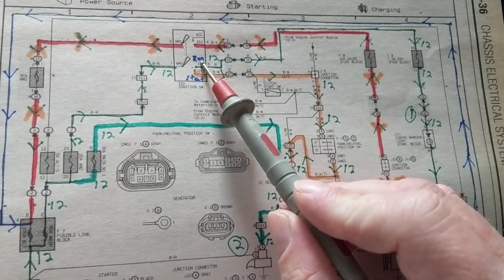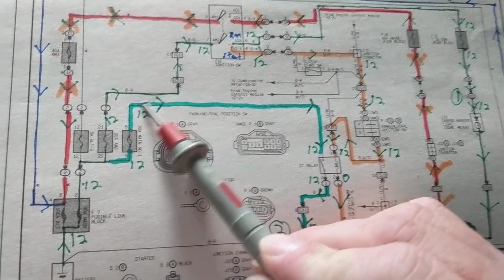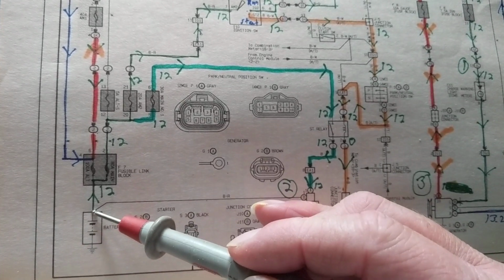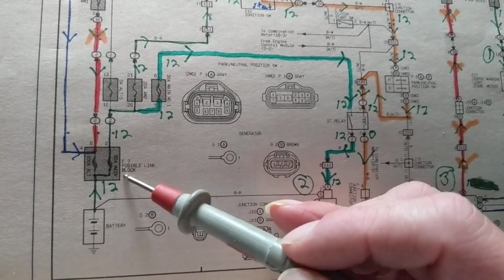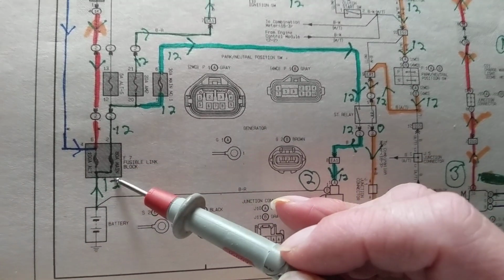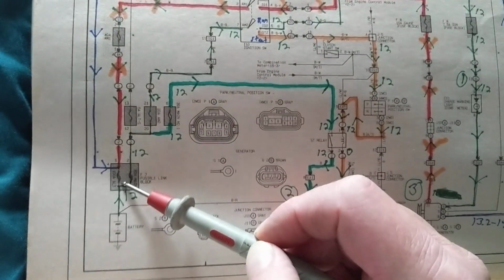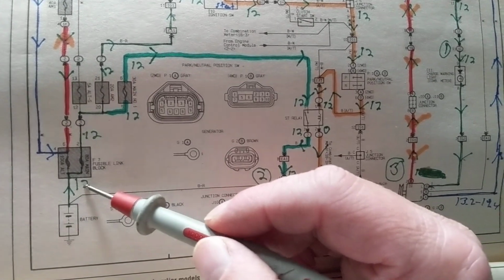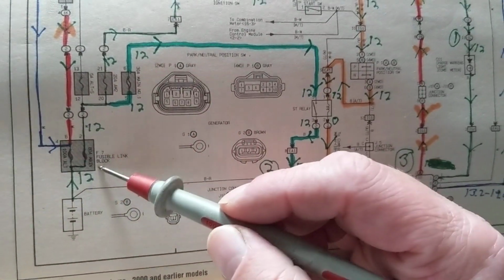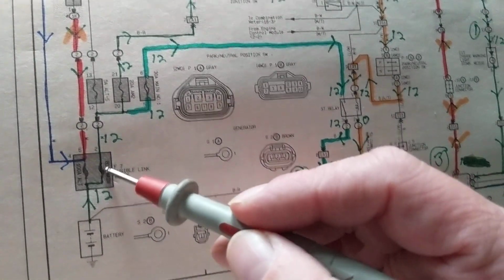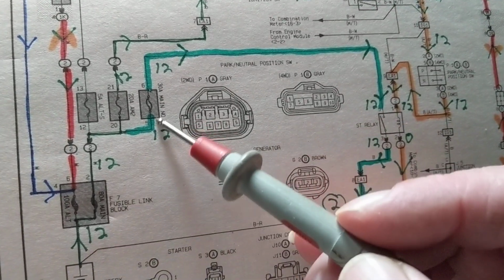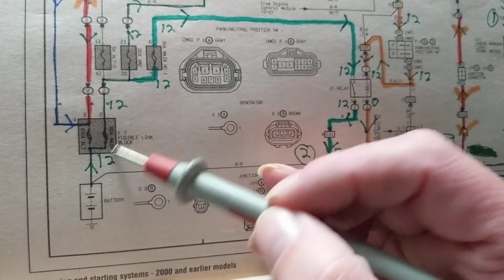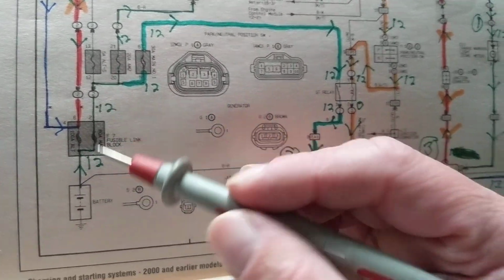Follow this line from here to here to here to here. This battery through this fusible block. And Toyotas and all these Asian makes, they like to have a common multi-fuse, they call a slow blow fuse, with two together in the same unit. Like a fusible link over here, or fuses over here, a protection device, but it's just in one unit. You replace the whole thing.